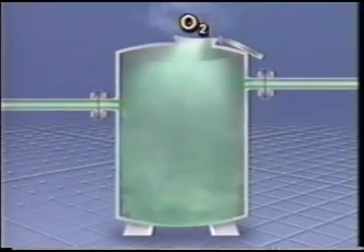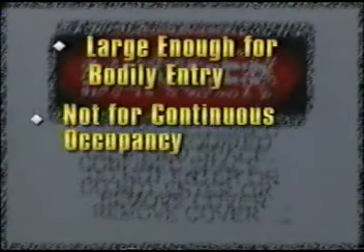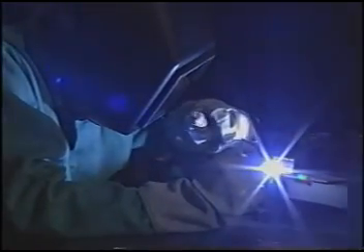A confined space is defined as an area large enough for bodily entry, is not designed for continuous occupancy, and offers limited means of entry or exit. The highest risk for entering a confined space is during non-routine work, such as maintenance, welding, or repairs.